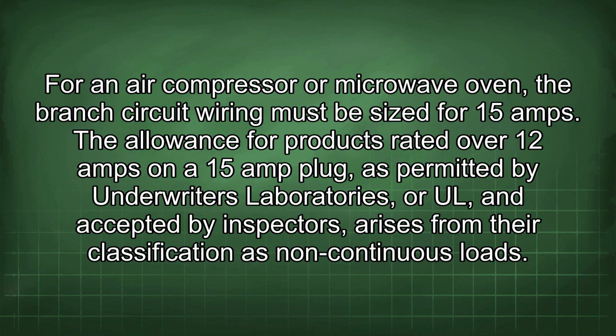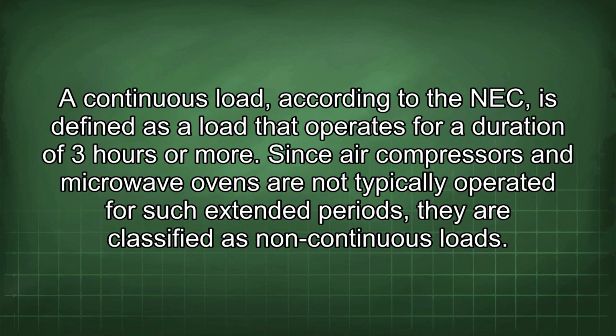The allowance for products rated over 12 amps on a 15 amp plug, as permitted by Underwriters Laboratories, or UL, and accepted by inspectors, arises from their classification as non-continuous loads. A continuous load, according to the NEC, is defined as a load that operates for a duration of 3 hours or more. Since air compressors and microwave ovens are not typically operated for such extended periods, they are classified as